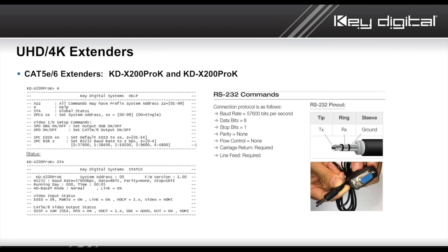What kind of display are we connected to, as we see at the bottom? Samsung 2014, according to the EDID file. Hot plug detection is good, right? So this is the input and the output we give you the status on. Huge, huge tools for those of you in the field tired of having HDMI problems and not knowing why.